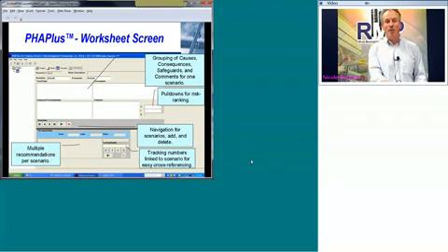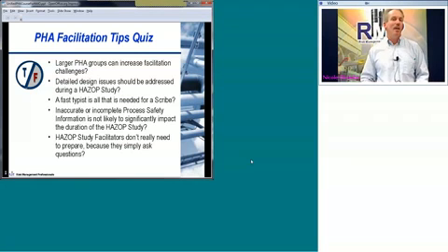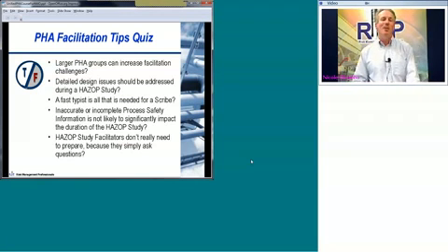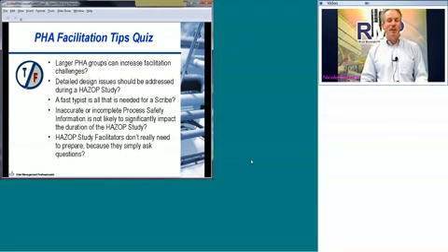What I'd like to do is take a few minutes, and it's a little tough to do a quiz on a webinar, but I want to use our standard quiz to talk about some of the key points that we've been discussing. True or false, larger PHA groups can increase facilitation challenges. Well, that's certainly true. With larger groups, you've got to be on your toes as a facilitator to keep it focused. Additional expertise is there, but as I mentioned before, you could also burn a lot of time with sidebar conversations and people bringing in other issues.